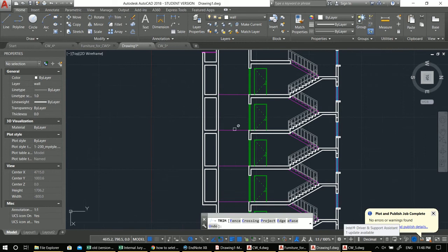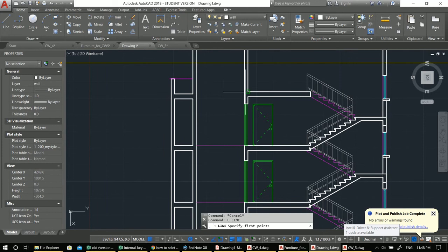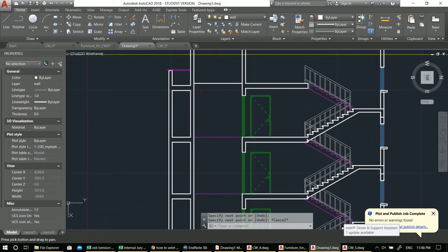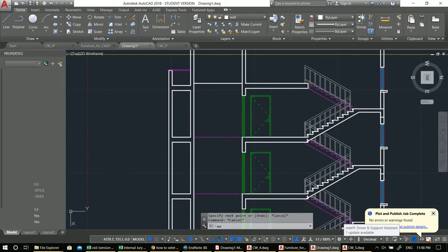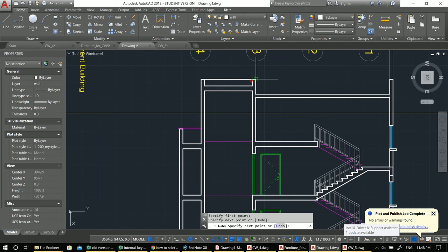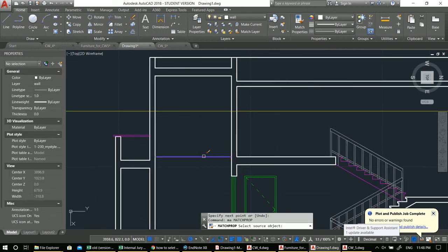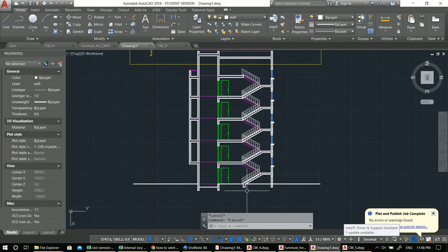Okay, now this looks about right, and this is how you do section in AutoCAD. You just use raise, you bring the line down just like you do in your paper drawings with T-square and everything. It doesn't have a magic wand that creates the section on its own, and you have to go ahead and start adding as much detail as you can.